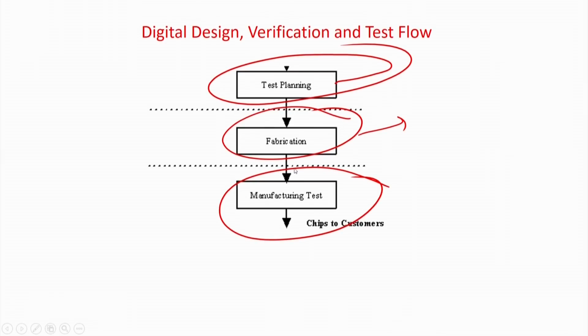What do you mean by good quality test patterns? Because all the chips have to be tested. If I give 100 test patterns to test a circuit, nobody will take it. I require very good quality two or three test patterns, because if I keep on applying test patterns, there will be 1 million chips to be tested. So it will take 10 days or 10 years to test the chips. But I require only 1 day maybe to test all the chips and ship them to the market.